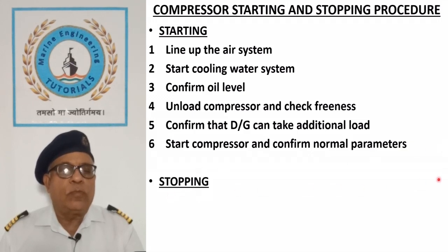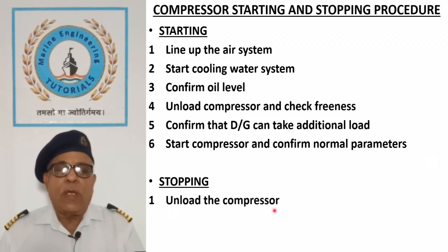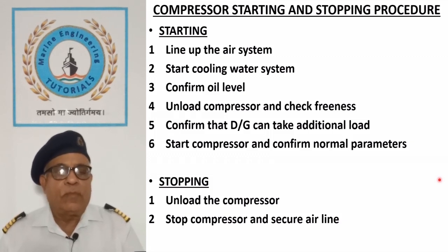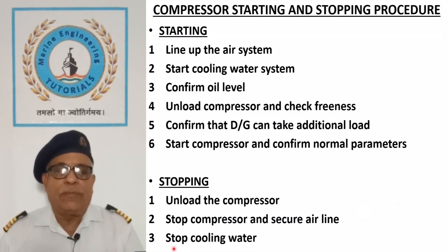Stopping. Unload the compressor. When the air receiver is pressed up, open the drain. Stop compressor and secure air line. Stop the compressor, put out the breaker and secure the airline valves. Stop cooling water. When the compressor cools down, stop cooling water.